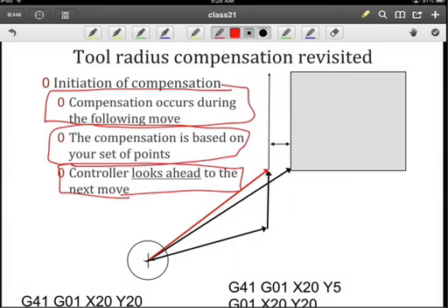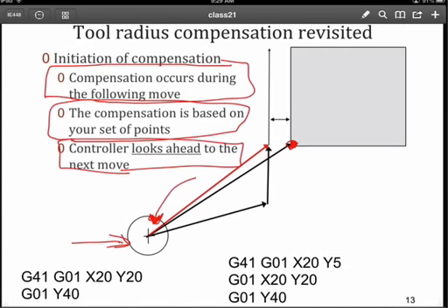So here we've moved the tool off of the workpiece, and the reason for that is before I use tool compensation, there's some finite time for us to interpolate from its current location to where it should be based on the direction of the move. So if I wanted to move to this location, I need to move a minimum of the radius, and that's probably not a good idea because you're cutting it close there. So I need to move off of that surface and then do a move, as you can see here, with my G41 to a X20 Y20 and then a G01 Y40.